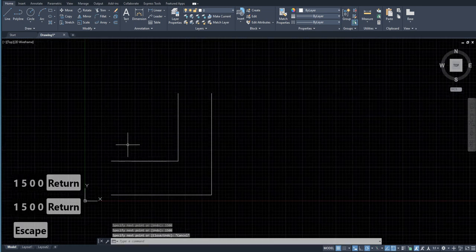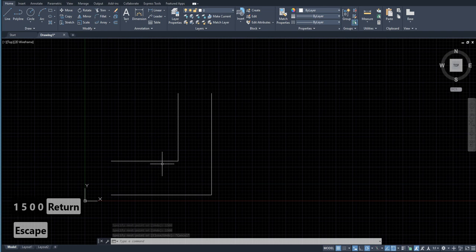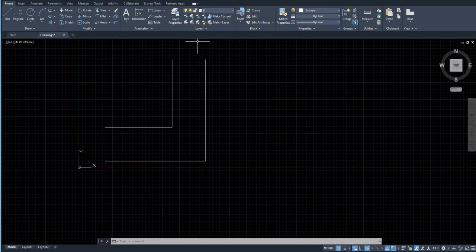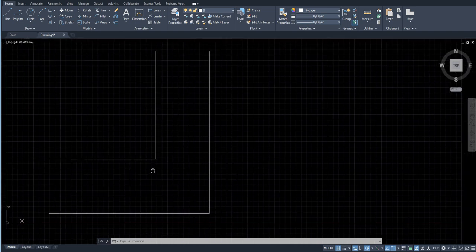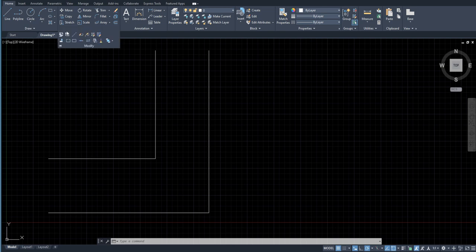If you saw, I just used very basic values for us to remember them, and the lengthen command is a pretty self-explanatory command. It lengthens lines or sections that are basically a part of lines, polylines, curves, etc. So the shortcut for lengthen over here is this particular badge, and also you can type the command lengthen